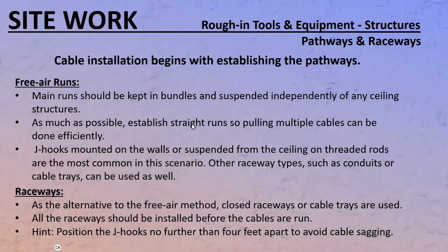As much as possible, establish straight runs so pulling multiple cables can be done efficiently, which is what I just talked about. If you have, let's say, a bunch of offices on the other side of the room, and you've got 12 wire boxes, you can pull as many as 12 wires at a time.